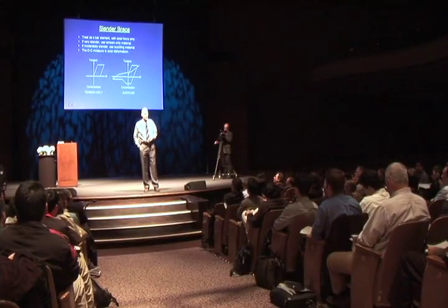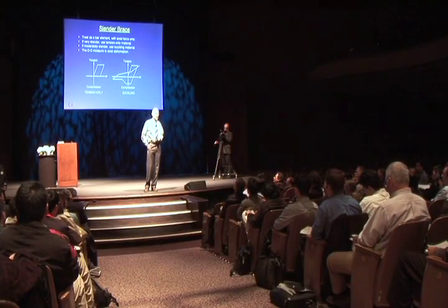Yeah, actually, there is one slide there which sort of addressed that. My first choice would be the chord rotation model if it works. If for some reason it doesn't work, my second choice would be a plastic hinge model. And if for some reason that doesn't work, my third choice would be a plastic zone model. I wouldn't go any further than that.